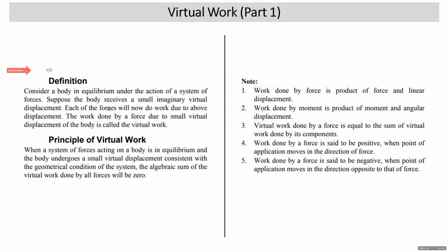In the chapter Equilibrium of coplanar forces, we had solved the problems by using equilibrium conditions. In this method, we give displacement to the body, and then all forces acting on the body will do work, and the algebraic sum of the work done by all forces is equal to zero. That condition is called the principle of virtual work, applied to solve the problems of equilibrium. All the problems of equilibrium of coplanar forces can be solved by the principle of virtual work, but we will restrict to what is normally asked as per our examination.